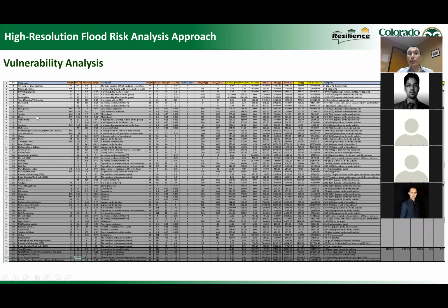Then we move up to the damage states based on the essentiality of other components, like when you lose your appliances, such as your refrigerator, stove, washer, dryer. So you lose many things. This is damage state two, which means restricted occupancy. You cannot occupy the building without these main things. You have your cabinet damage, your washer and dryer. Similarly, damage state three is when the water goes very high and hits your upper cabinets and damages all your counter components and valuable items in your building.